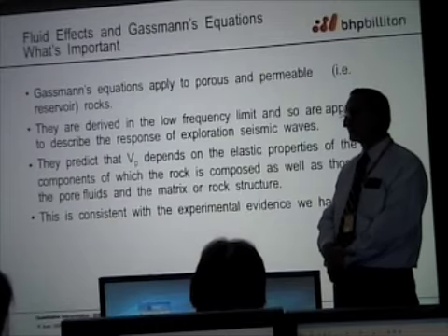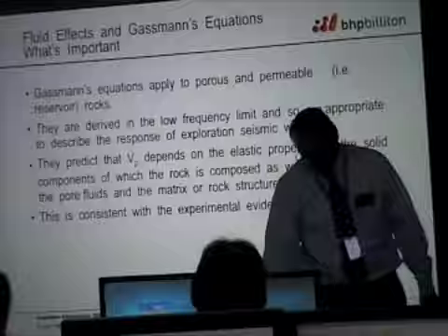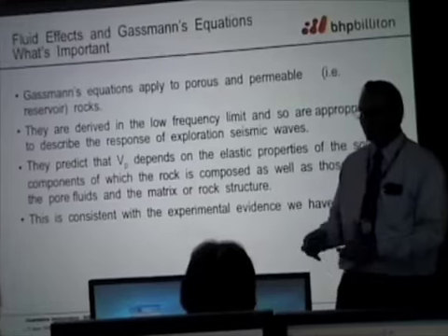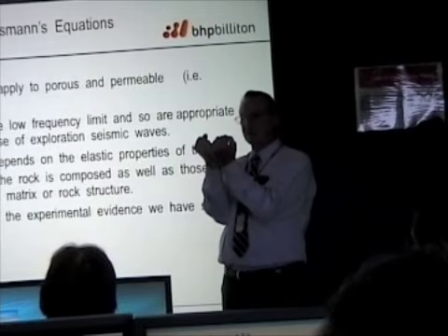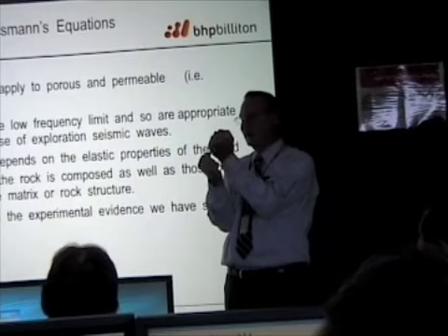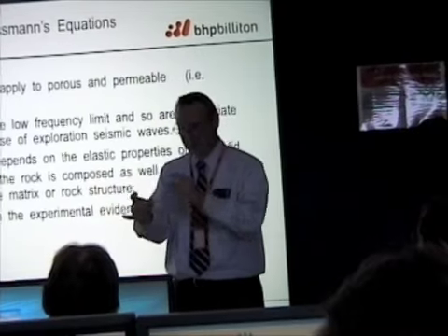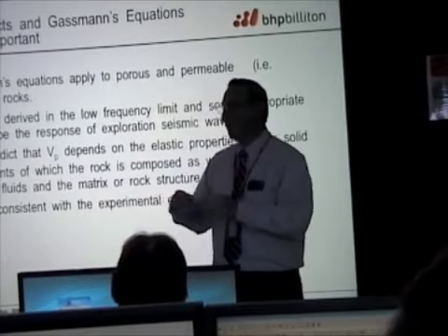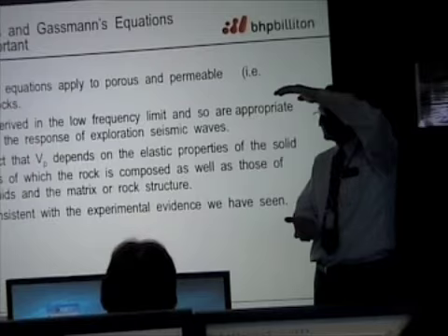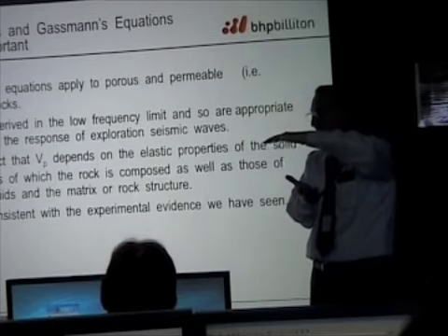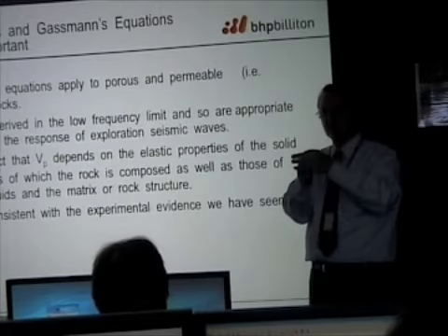And in fact, Gassmann's next paper in 1951, what he did was say, look, I'm going to consider a simple system where I'm going to put a bunch of elastic spheres together in close packing. Okay, I'll make a row of spheres, and then I'll put in depressions, more spheres of the same size, all of the same material. And I'm going to consider the deformation of that body as I load it with a stress. How much does it change? And of course, he used Hertz theory for the contacts of the spheres.